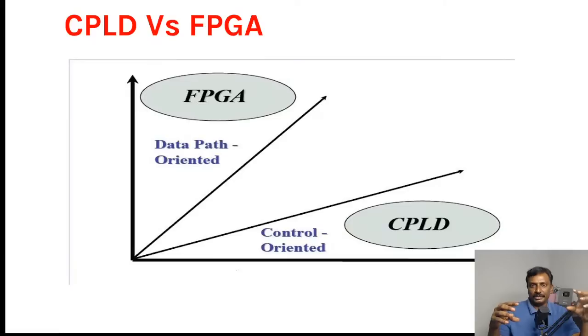You will have the GPIO pins, so you could customize any GPIO pins and any number of UARTs you want. For example, if you take an 8051 microcontroller, you have a single UART. If you want two UARTs, the next option is to go with a software UART. If you want more than 2 or 3 UARTs, there is no possibility on the 8051. Whereas in a CPLD, even if you want 5 UARTs, you could design 5 UARTs and customize that.